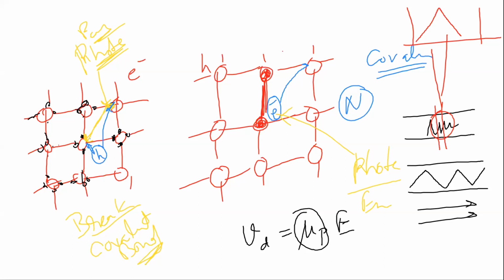In digital we definitely don't always need a resistor, but in analog, for example, we need resistors. So if I want a high value resistor for a given amount of area, then obviously I want to choose a P-type, because that will give me a 2.5x area advantage, which in semiconductors is huge.